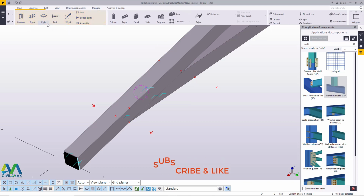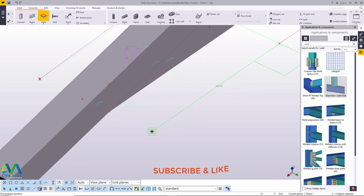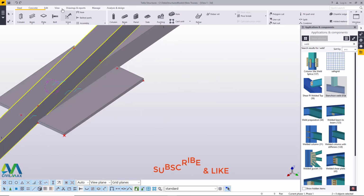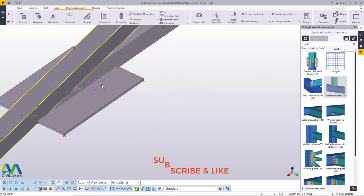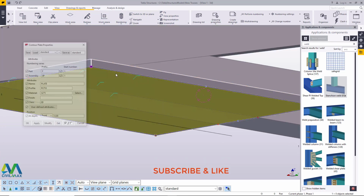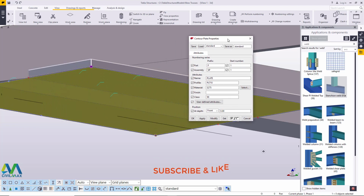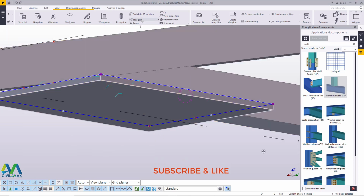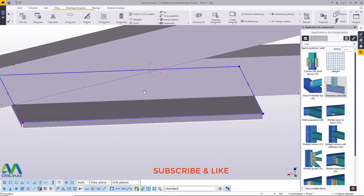I'll come to steel here and pick plate, and I want to create a plate right there. Let me just zoom closer. I've created my plate, but somehow it slightly clashes with my bottom chord. So I'll double click on my plate here, come to position, click this drop down arrow and pick behind, and that will shift it to the bottom end. It will make the plate flush with the bottom end of our bottom chord.